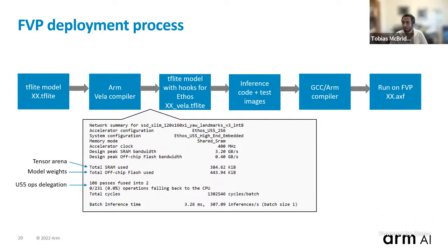Then Marconi's asked, will the device support speech recognition, keyword spotting applications, and what hardware audio interfaces does it support? Yes, it will. We actually have a keyword spotting demo that is also using the Ethos unit for our board. We have I2S microphones on the eval board, and we also have PDM interfaces in the device, so you can capture audio from both analog and digital microphone sources. Brilliant. Thank you for that.